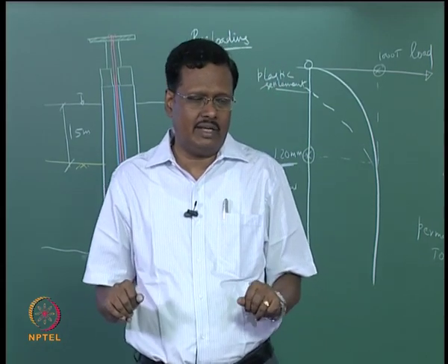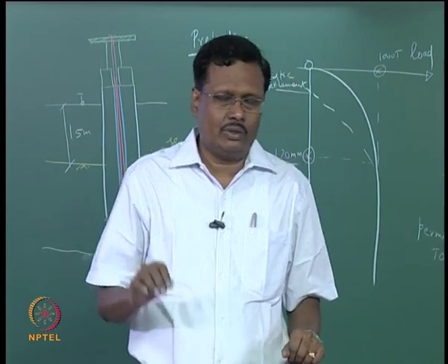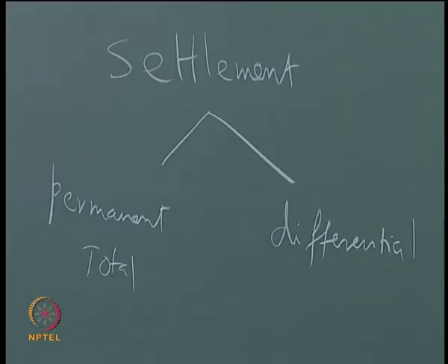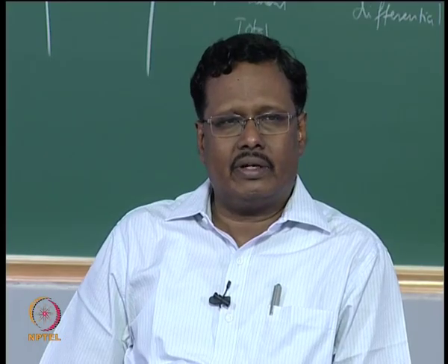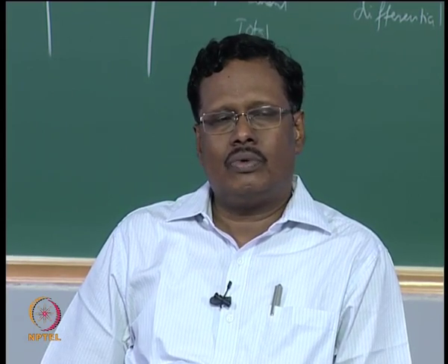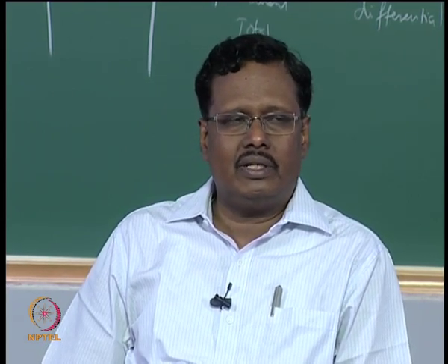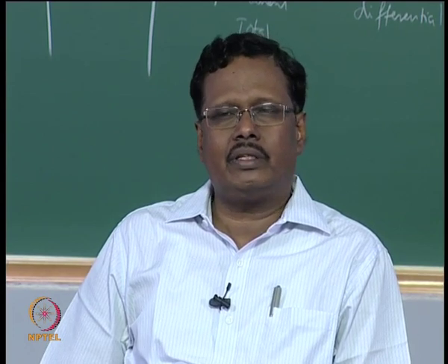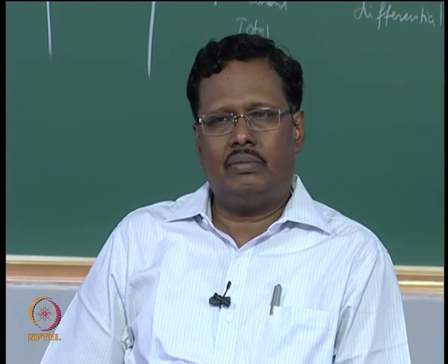So in civil engineering practice you should know the acceptance criteria. It is there for all behaviors. Crack width, what is the permissible crack width? 0.004 times the cover. If the cover is 75 millimeter, you can permit 0.3 mm. If the cover is 50 millimeter, you can permit only 0.2 mm.